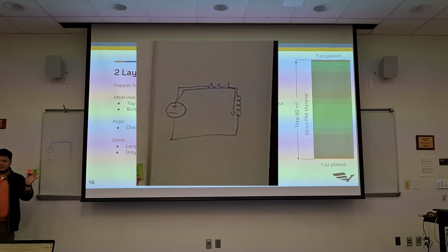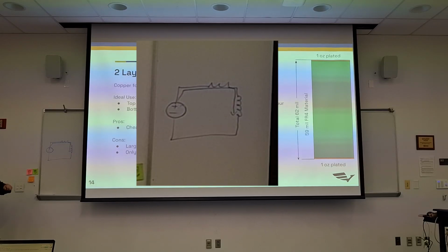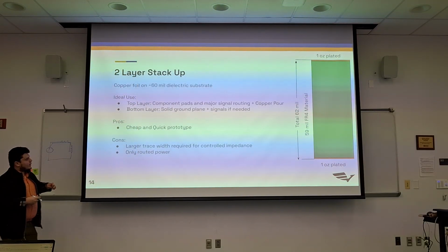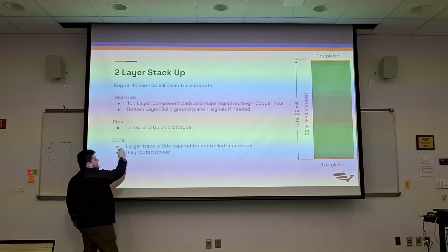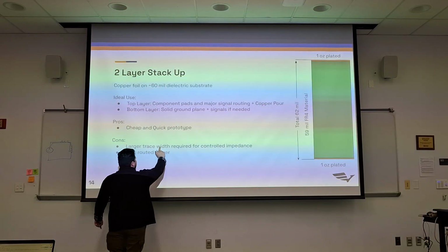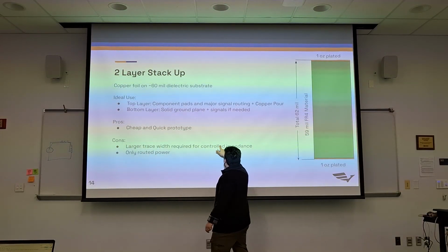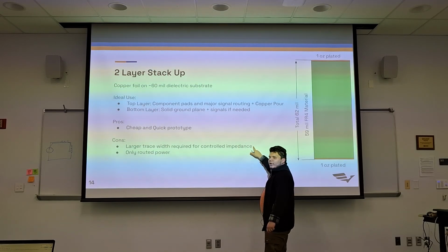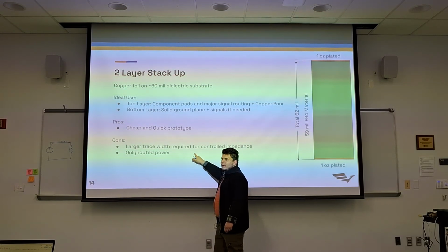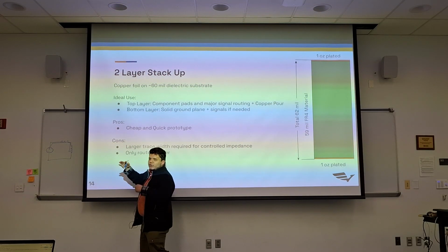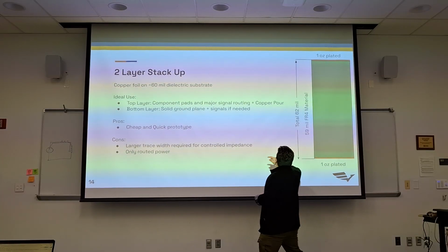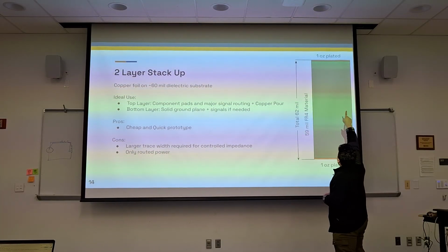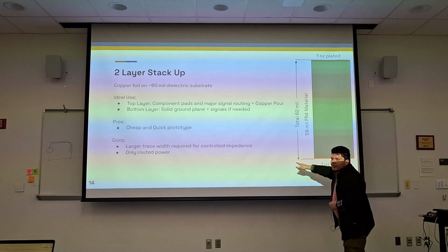This is just kind of a rule of thumb. It's always going to try to go underneath the trace. So if we route everything on, let's say where this line is on the top layer, we're going to want to come back down immediately below it to make that loop as short as possible. And so you always want to have solid copper underneath.